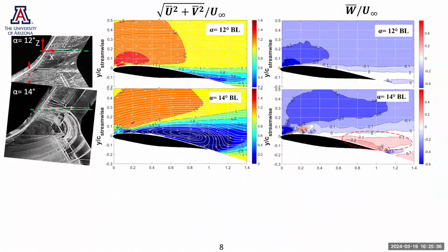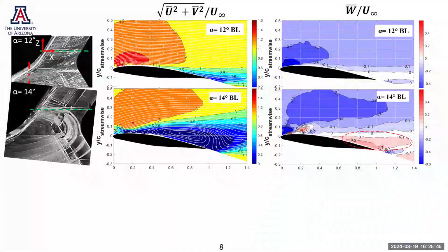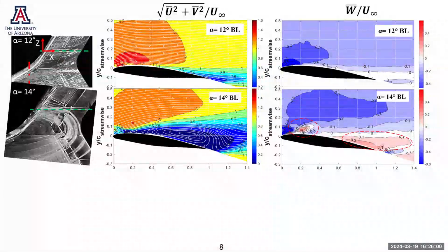At the nose, we do not have as strong of a flow acceleration. And here, we have negative flow velocity marked by the flow moving inboard to re-energize this vortex core. And then there is this tiny structure in red, which identifies a new vortex being developed on the outboard side of this PIV plane. So basically a new vortex for the outer wing.